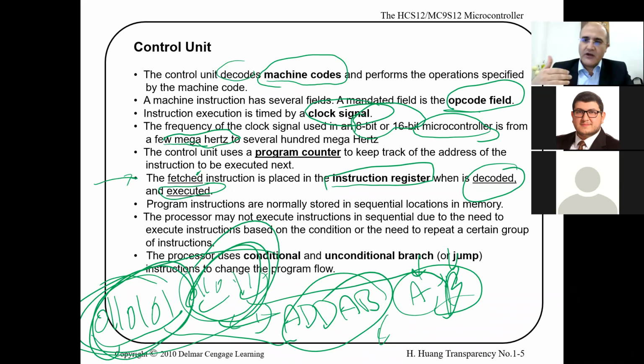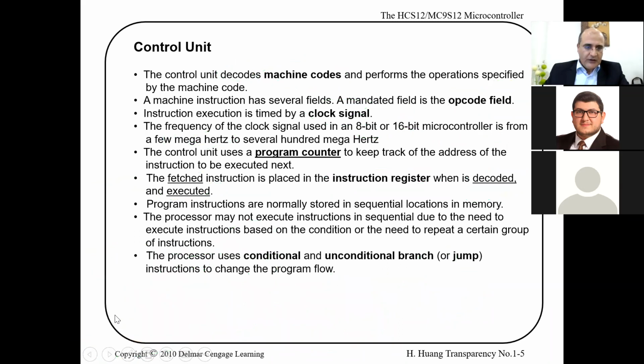In our microcontroller, this signal that we get from the oscillator, we can process it in a clock block. And we have a PLL circuit, we're going to cover it later. And we can multiply the frequency up to 48 megahertz, so we're able to generate up to 48 megahertz in this microcontroller we're dealing with.